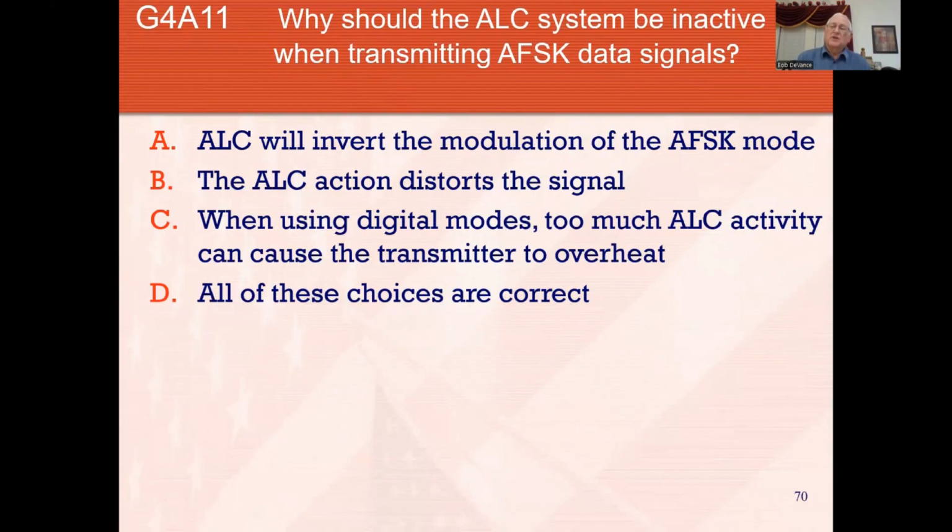If the ALC is showing a whole lot of activity, if it's trying to control your radio, then it may cause your transmitter to overheat, that's for sure. It can also indicate that it's jacked your transmitter up, so you're distorting your signal.